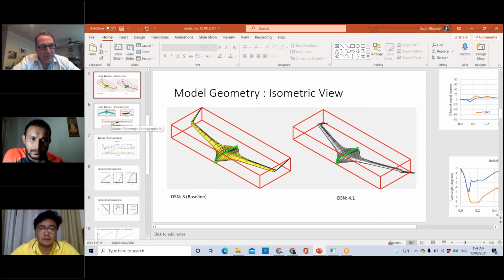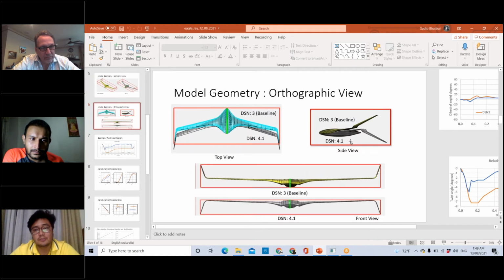So with that we had a lower induced drag and higher lift to drag ratio, provided the total span with the sweep was the same. Whatever the total wingspan is, it was just rotated in the forward direction. Got it. So unsweeping it was improving the vortex drag.